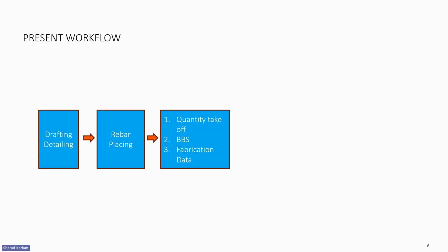And once the rebar has been done, we can get the quantity takeoff out of it, whether we want the quantity of concrete, how much cubic volume is needed, or how many square meters of area have to be done. So we can get all these things. We can get the bar bending schedule, as well as the fabrication data.